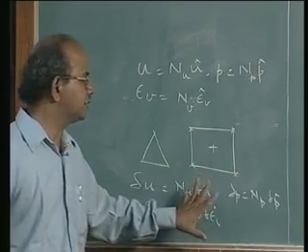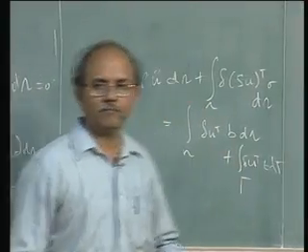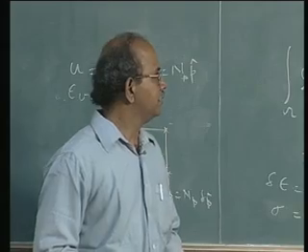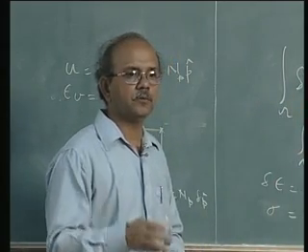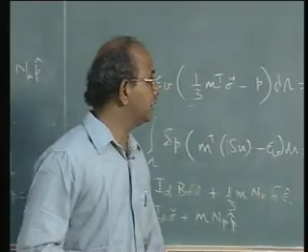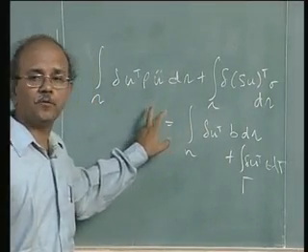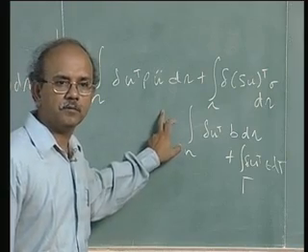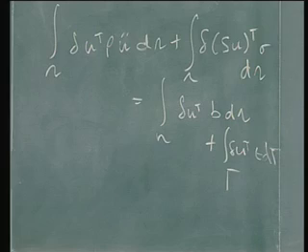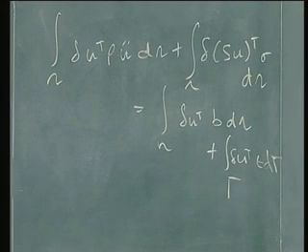So substitute these equations here. Let's see what you get. Of course, delta U transpose, you have delta U hat N transpose. Note that this is the inertia term. If you are doing dynamics, this term will be there, the U double dot term. If you are not doing dynamics, the term is out. So please look at these two terms and write that down.